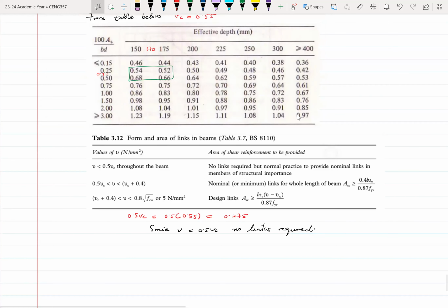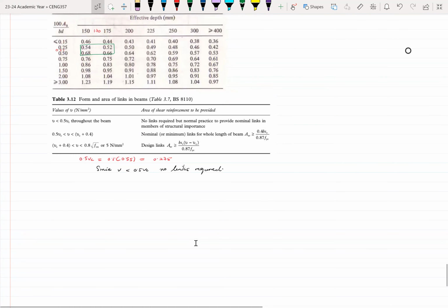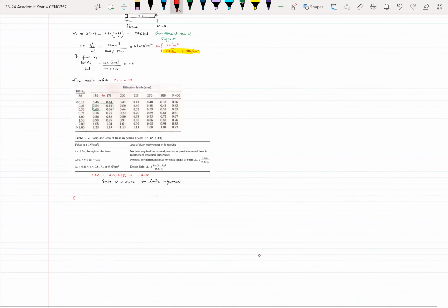So this is for the main bar, main rebar. Any questions? Okay. This is for the main rebar. We need to look at the transverse rebar. And for the transverse rebar, for this type of beams, we normally use the minimum. So, number 6: check shear stress.